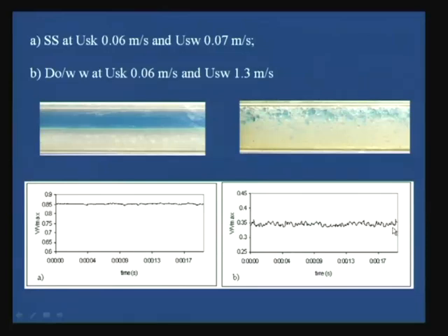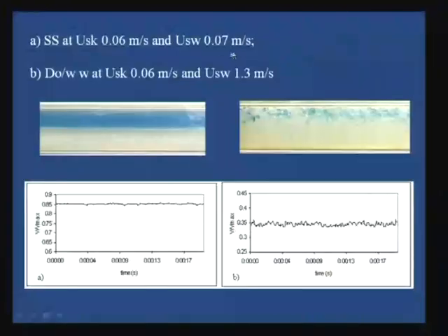Is it correct? What we were doing, the amount which was transmitted, that was converted to a voltage signal. How was it converted? The voltage signal was high when water was the continuous phase, it was low when kerosene was the continuous phase. The circuit was designed in that particular way. So, whenever water is in larger proportion, we have a lower voltage. Whenever kerosene was in larger proportion, we had a higher voltage.